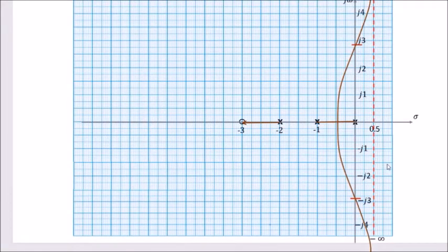And also from this root locus, we can know the performance of the system, whether the system operates under overdamped, underdamped, undamped, and so on. So, for example, if the location of the pole moves from the original location to the other location, for example to here, that means the system changes from the overdamped to the underdamped case.